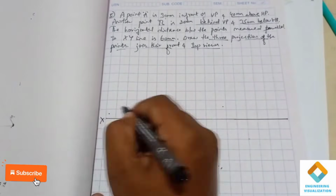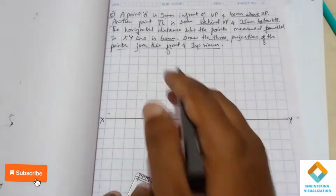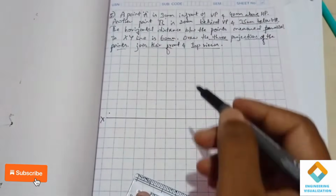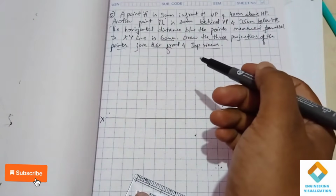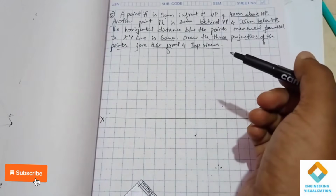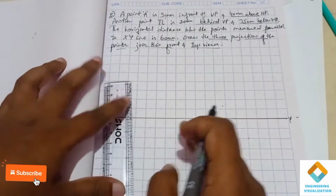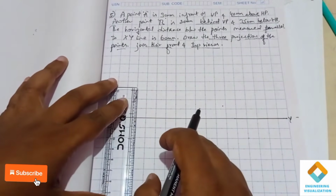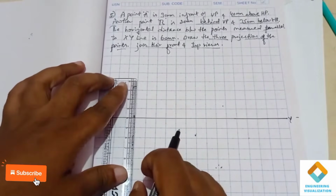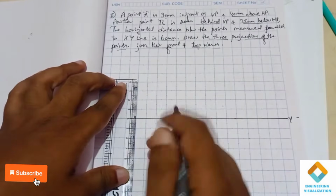So this is X, this is Y. Now first we take the point A. The information is 30 mm in front of VP and 40 mm above HP. Thirty mm in front of VP and 40 mm above HP means it is the first quadrant. So 40 mm above HP means it is a front view, and I am going to construct it here. Front view we always get above the XY line.